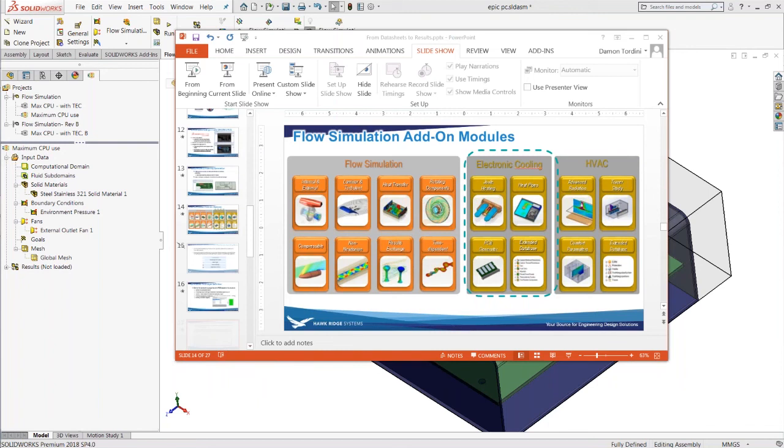It has a table that shows all the layers, whether it's the dielectric or the conducting material, and what the thickness is, and also, of course, what the order is. And so that, combined with also looking at the top-down layout of where the traces are, would help you input what these layers are and what the coverage is of each one. And other board layout programs are going to have this same type of info, whether that's Altium Designer or PADS or any of the others.